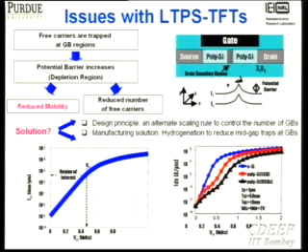So what we did is look at different process technologies, and it turns out that you can use a laser annealing process and still be able to get a reasonable transistor down to about 200 nanometers or so. Now, if you are using, for example, a process with a maximum temperature of about 400 to 500 degrees centigrade, you can get grain sizes of the order of about 200 nanometers or so. Then one can potentially think of having a device where there's going to be a maximum of 1 or 2 grain boundaries. And then what I really need to do is figure out what is going to be the degradation in the transistor and so on. But there's a very interesting thing to note in such a technology right here.